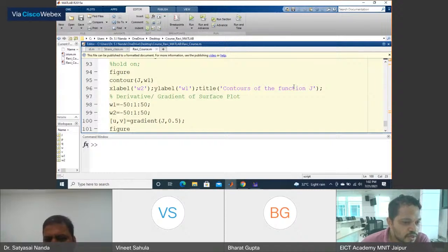How to increase the resolution of the graph? You can use proper scaling for improving it. The scale you can set to 0.3, 0.4, 0.8, whatever you need. Or if that is not working properly, then in MATLAB, whenever you are saving the picture, you can save it as an .eps file and import it in LaTeX. The EPS file will always have very good resolution. Even if you multiply it by 20 or 30 times, the resolution will not deteriorate if you are using EPS.